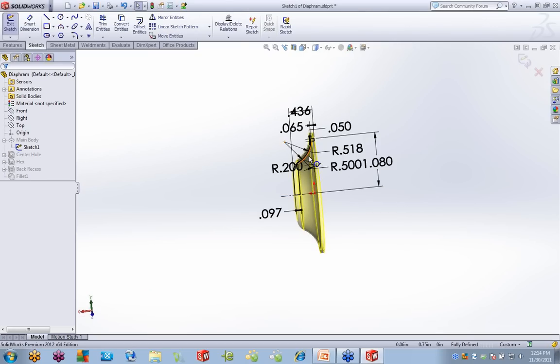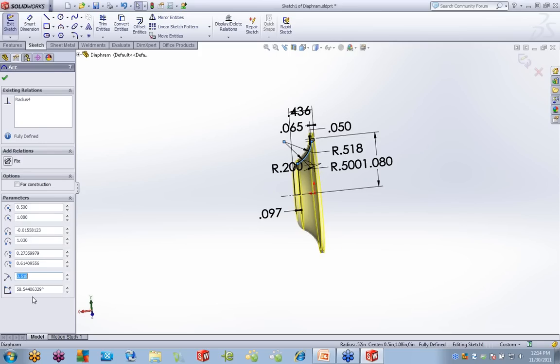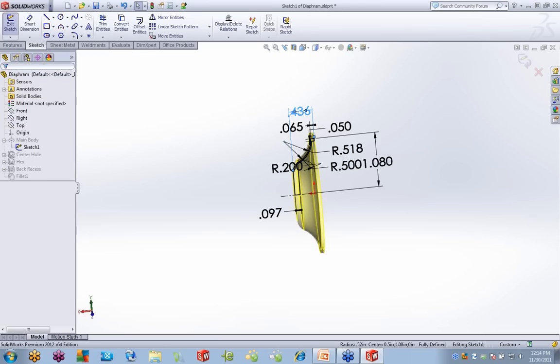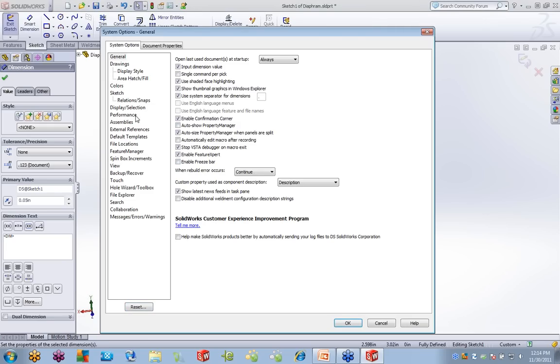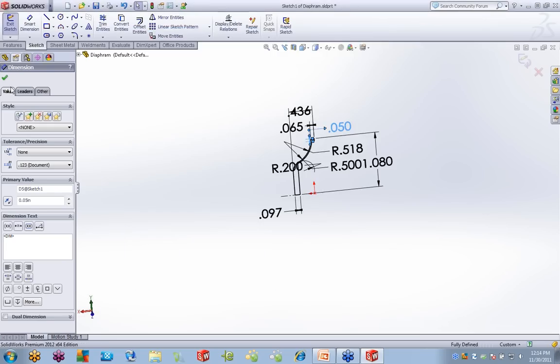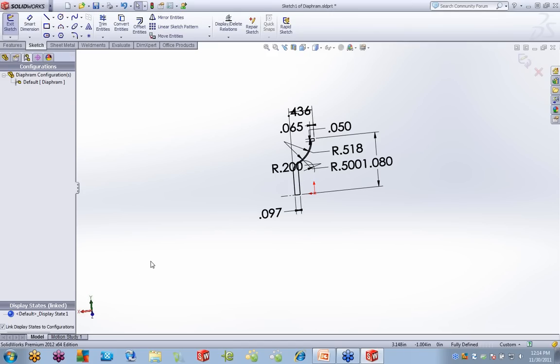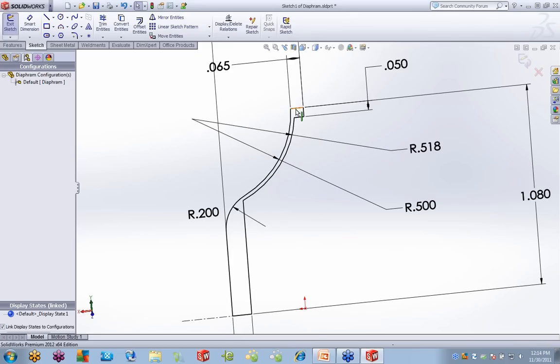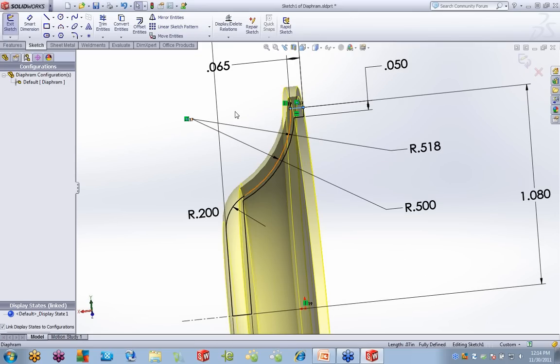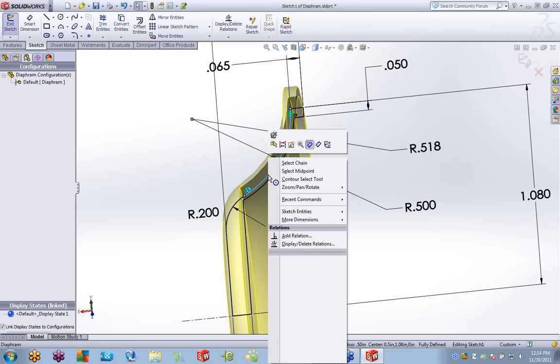If I select any item from within that sketch, you can see that the Property Manager for that sketch item shows up automatically. If I pick dimensions, we're all used to this way of working, that the Property Manager kind of works right along with us. But if I wanted to, for some reason, always focus on, maybe I'm working on configurations, I wanted to keep my configuration tab up so I remembered what configurations I was dealing with. By turning that off now, I can make my selections, and notice it doesn't trigger the Property Manager to come up at all. Okay. Now, how do we get that up from here?